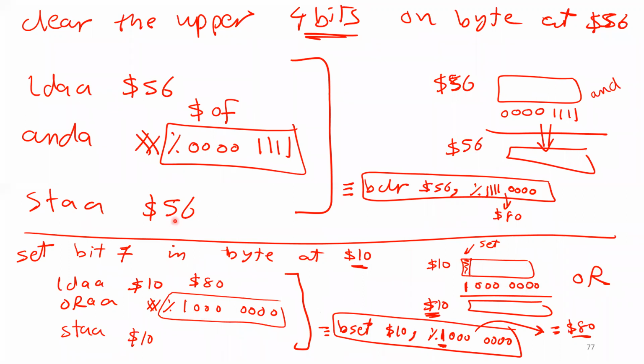That is why, similar to what I did in the previous example, number one, I have to load. So memory location number 10, I'm going to load it into register A, as you see here. Number two, I'm going to work on register A. And you can put this value in binary, but please count the number of zeros, because if you forget one zero, you know what's going to happen? This will be bit number 6, not bit number 7. You got the problem?